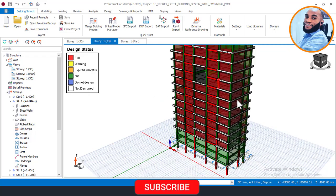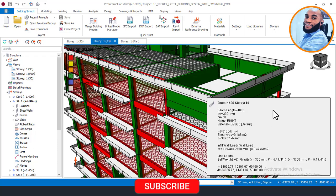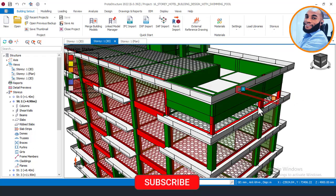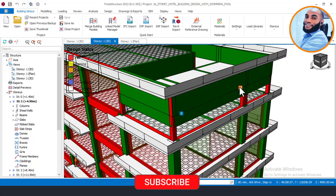If you check at this pool area here, at the top of this pool area, you can see that the columns here that we reduced the size of at part 9 are still having some failures. So we also check on that. That is why we now perform the interactive design.